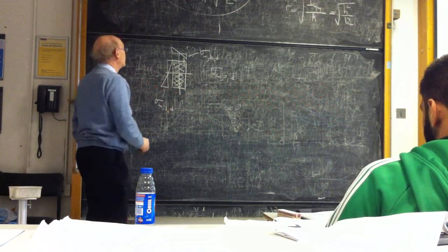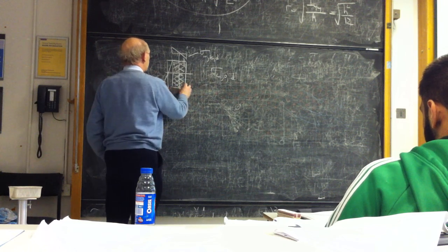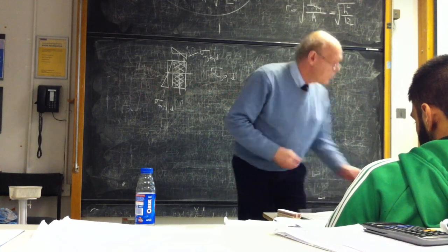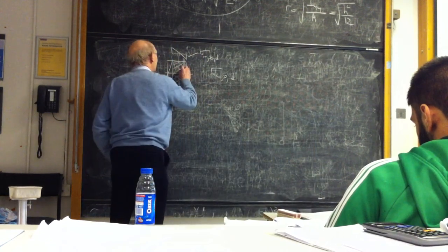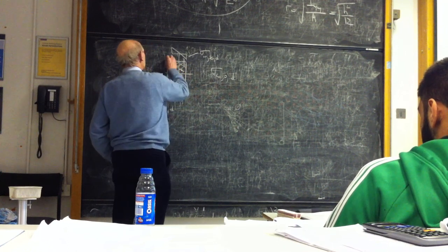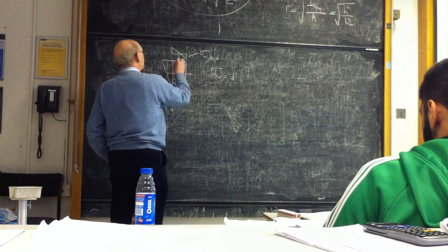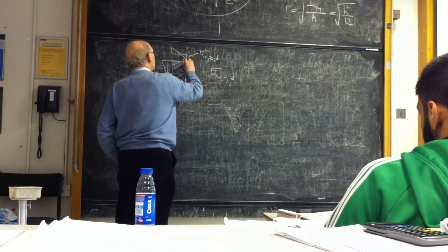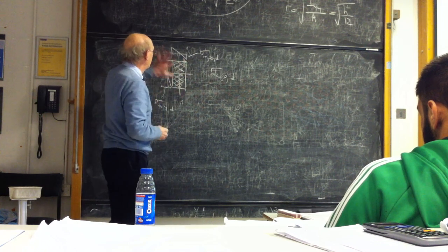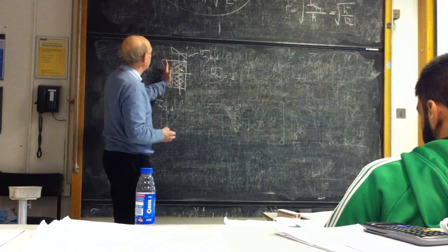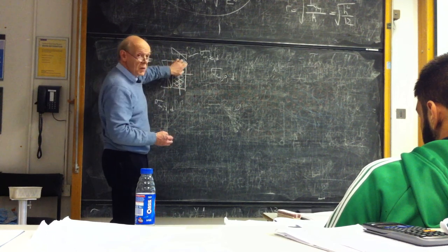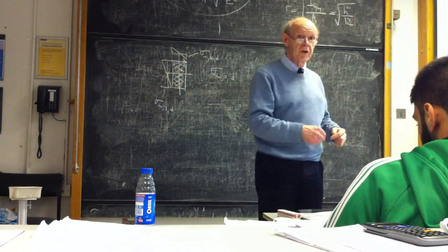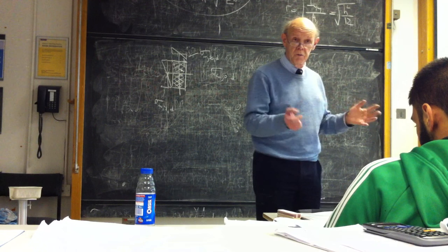And somewhere, perhaps in this corner, where's the load put? Bottom right, I think. Top. The load's there. So really I should probably have drawn this the other way around to make it clear. If the load's there, the worst stress is going to be in that corner, because it will pick up the compressive stress on the whole column, it will pick up the bending stress about this axis, and it will pick up the bending stress about that axis. So somewhere there will be a point where all the stresses are compressive, and if it's going to fail at all, because they fail in compression, this is where it's going to fail.